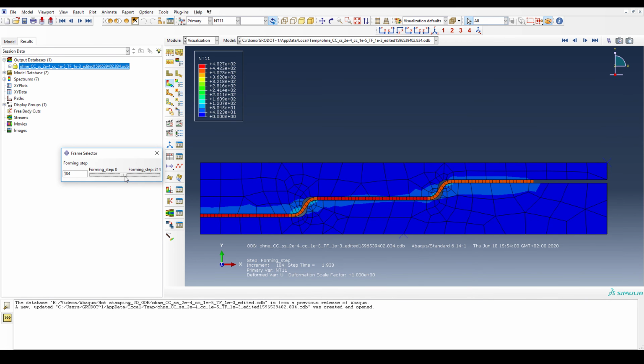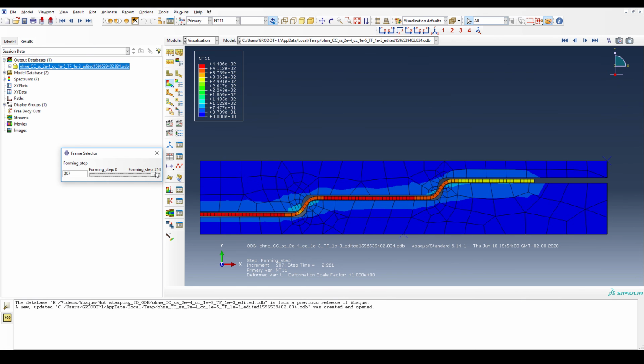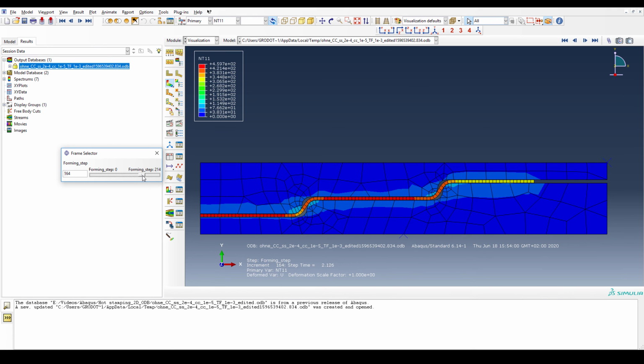And if we look at the step time, up to 2 seconds is where the forming step ends, and then from 2 to 2.1 we only have the transfer of heat, and we see that the simulation has a lot of problems to initiate the retraction phase, and this is where we need the stabilization, because this is, for a lot of different reasons, quite challenging for the solver.